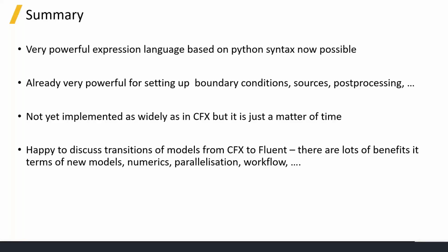But the other reason is that I'm really promoting now transferring your work from CFX to Fluent. There are so many benefits in terms of new models, numerics, parallelization, workflows, particularly with the meshing templates and how you can just flow through the workflow, that if you're a CFX user and you're not using really advanced turbo, and I mean advanced turbo, I don't mean doing a fan, I mean, if you're using anything like a blade row model, then yes, stay with CFX.